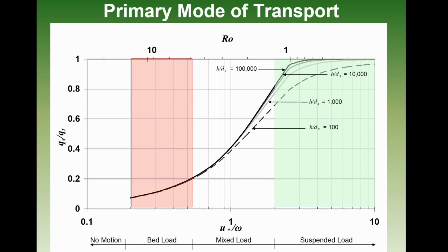You want to find out where the mass is. Well, you've got the dog in the bed load and the tail in suspension, right? All the big mass is really at the bottom. Make sense? And if you go above 2, which is another nice number, so 1/2 and 2, now you get to 80% in suspension and 20% is the dog.